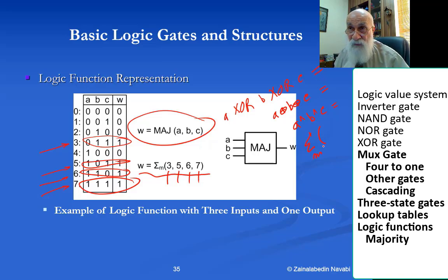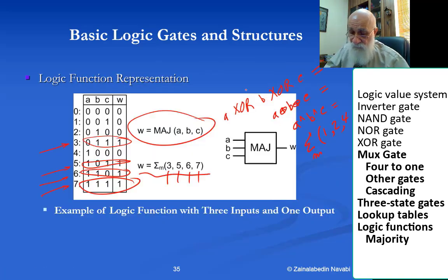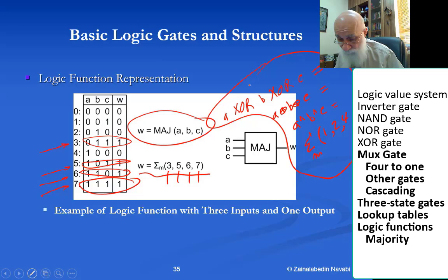XOR of the 3 inputs is 1 if the number of ones is odd, that means 1, 2, 4, 7. Okay, which are the numbers 1, 2, 4, 7 in this case, and therefore XOR can be represented as such as well.